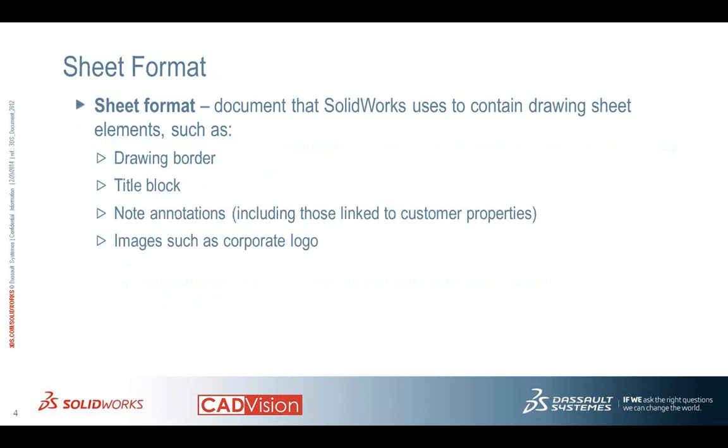Okay, sheet format. So what can we set in the sheet format? Inside it contains drawing borders, title box, all the notes and notations, and images such as a company logo. All these, the title box, notes, and so on, can be set inside the sheet format only. So inside the drawing templates, you have the sheet format, and inside the sheet format, you can add in all the notes, borders, images, and so on.